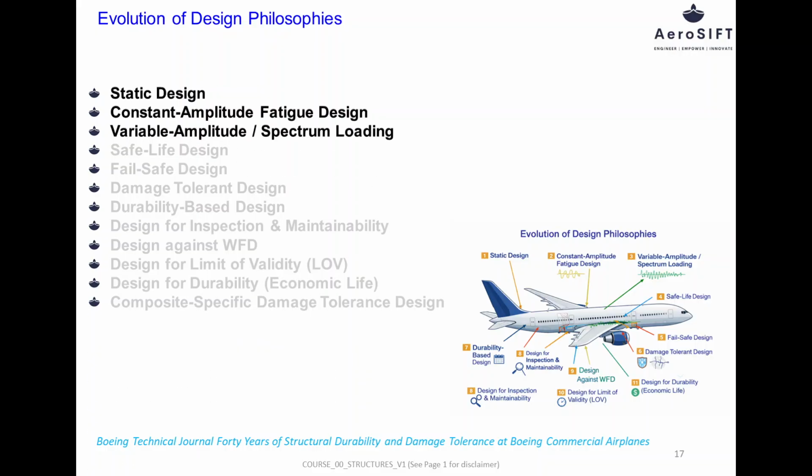To better represent real operational conditions, variable amplitude or spectrum loading was introduced. This philosophy recognizes that aircraft experience a wide range of loads during different phases of flight, such as taxi, takeoff, cruise, turbulence, and landing. These varying loads are converted into equivalent damage cycles using cumulative damage concepts. This approach significantly improved the realism and reliability of fatigue life predictions.